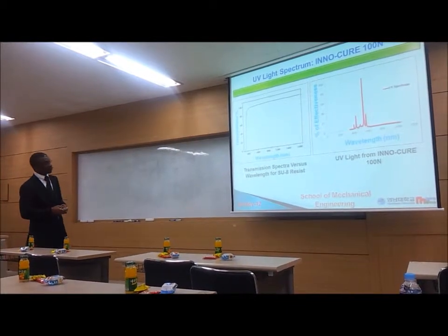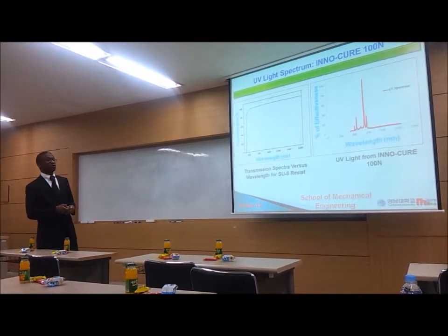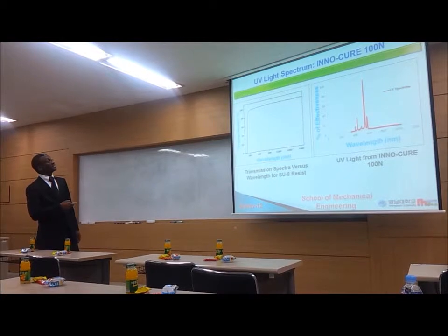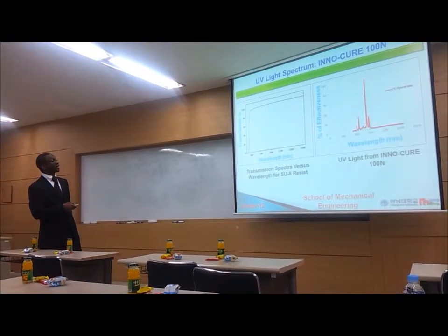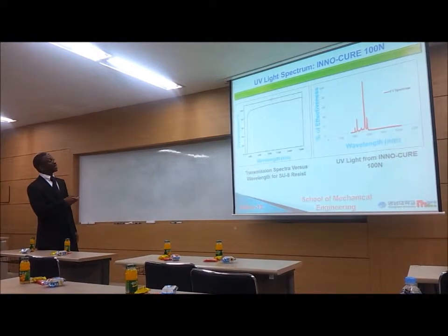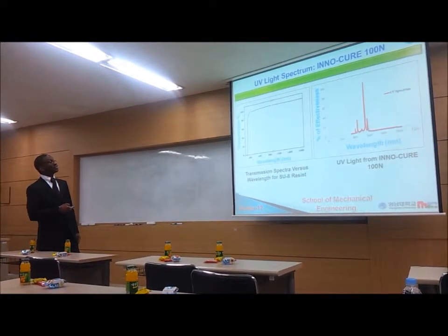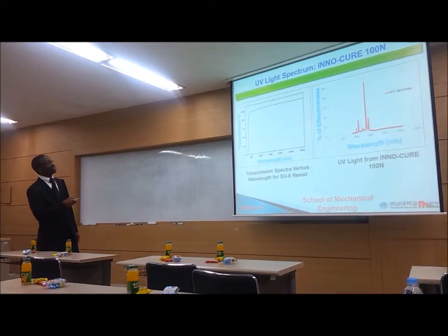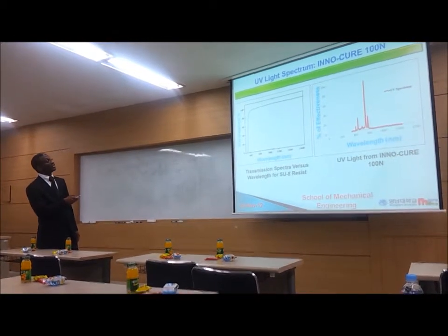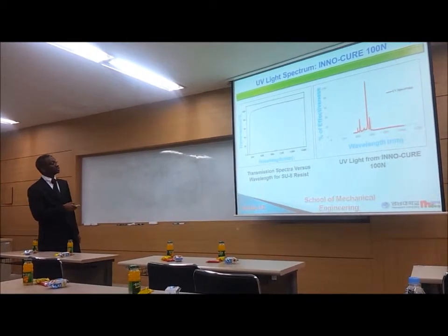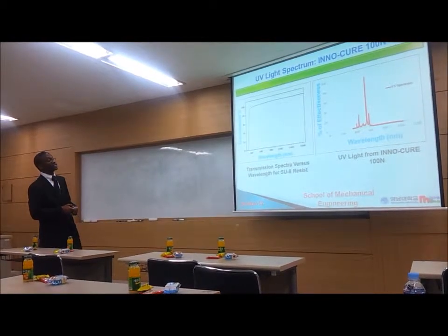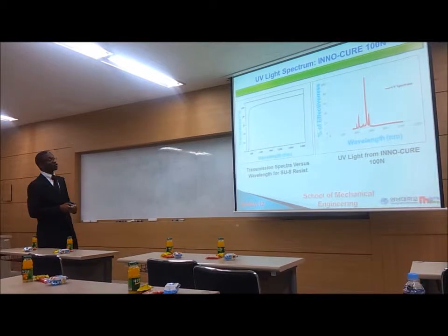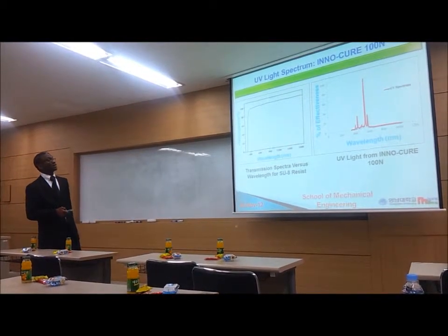But before we go to scan, we had to understand what is the wavelength we need to scan our SU8. Because the developer of SU8 has analyzed and shown SU8 can be scanned very well if the wavelength is in this range from 400. Then we measured ours, we found it was around 600. So we concluded here that this system will scan, it will make our mask.